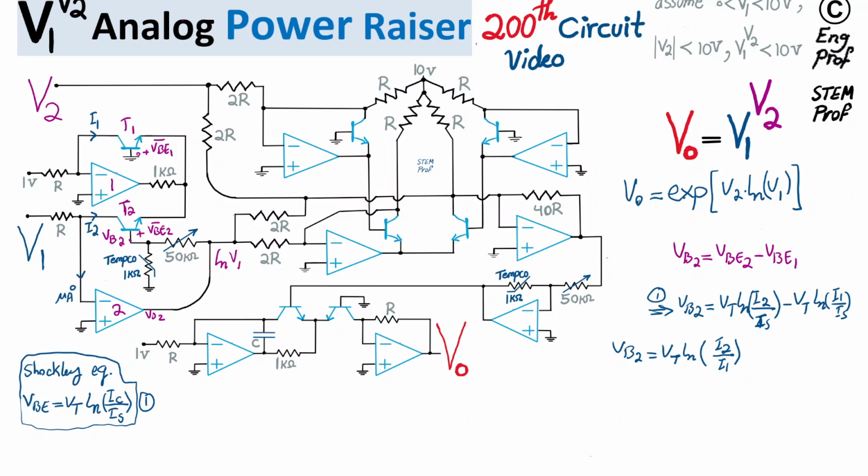And then because of the virtual short of the OpAmp with proper feedback in the system, we have ground as the positive terminal, and the virtual short forces the same voltage at the negative terminal, which is 0 volt, basically the negative terminal as virtual ground.